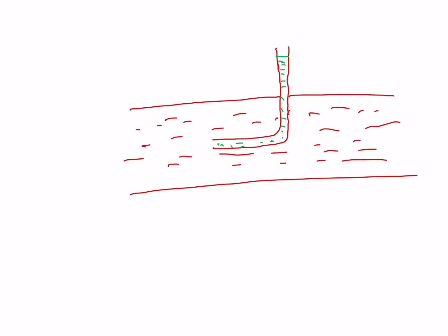Its fluid goes up to this height. So this height H is your stagnation height. This device is your Pitot tube. You can use piezometer also. If you insert a piezometer here, you will get static head, small h. This is your static head.